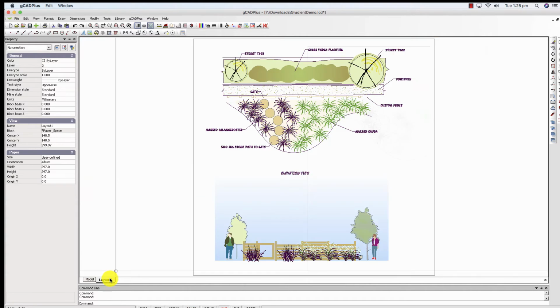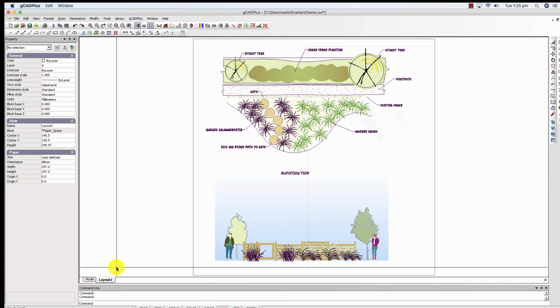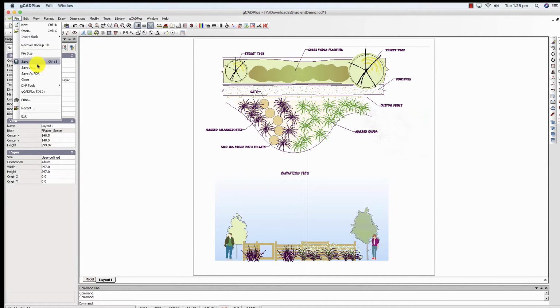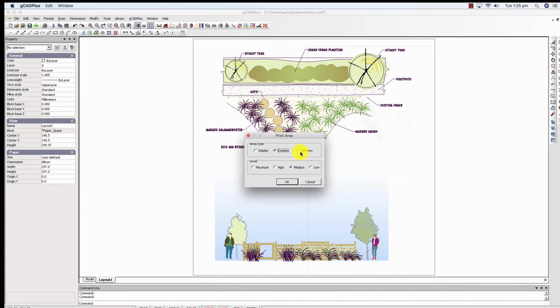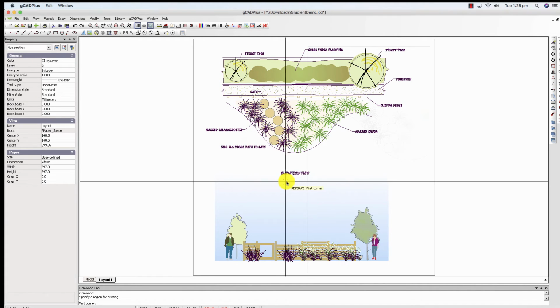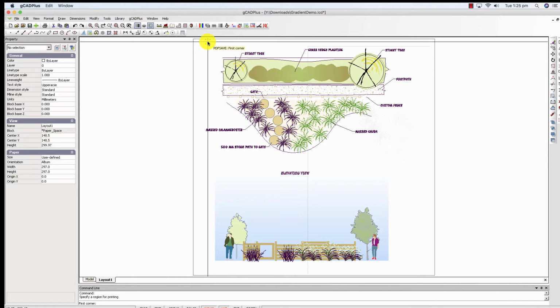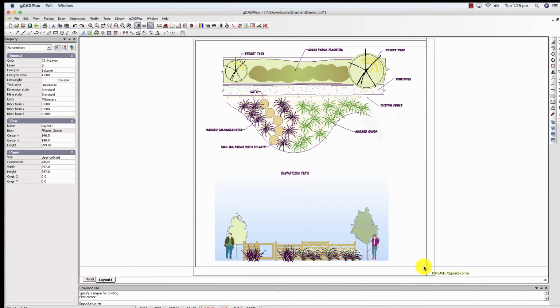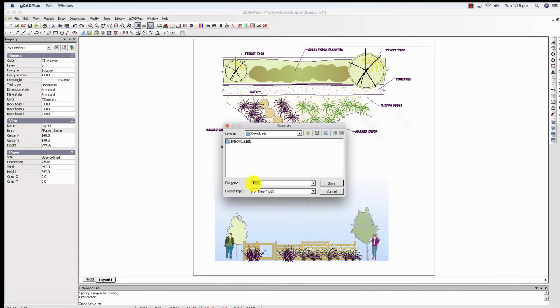If we come to a layout view, there's the layout. Let's just see if we can save a print of that. So we'll go File and Save as a PDF. We'll put a window around it. I won't go for the maximum resolution. It might be a little challenging, but we'll put a box just inside the floating viewport here, and we'll call it, in our downloads folder, we'll just call it test.